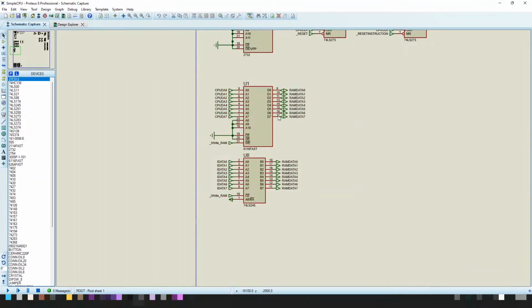Now the program RAM is a little bit easier, kind of, because it's only a simple 8-bit piece of memory. The RAM data signals here, 8 bits, are input and output. And we have the CPU data address register represented here, which is also 8 bits. We have a signal here which on low writes memory rather than reads it. If it's high, then these outputs are going to be what is in the current RAM at this address.